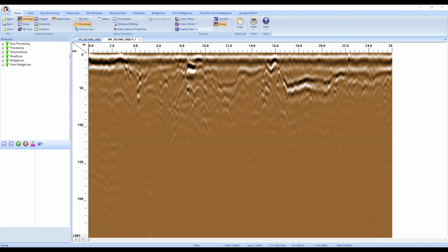Once you point to your working folder as grid normal, then specify that you want to auto load the files. It'll grab all 91 of them, put them in the right location, and then all you should need to do is reverse the 3 that need reversing, and then, well, the 10, I think, that need reversing, 28, 29, and 30, and then 92 to 97. That should save you a lot of time.